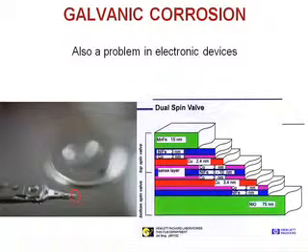And that information has to be written onto the disc, and read from that disc, using these little recording heads that fly above this spinning disc. The structure of these heads is very specific for physics reasons, to get very sensitive sensors for bits of magnetic information, little magnetic fields. And to get higher and higher densities, to get larger and larger disk drives, which is what's happened for decades, the way you do that is to make the magnetic domain smaller and smaller. So you need very sensitive sensors.